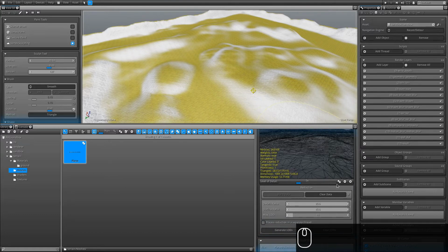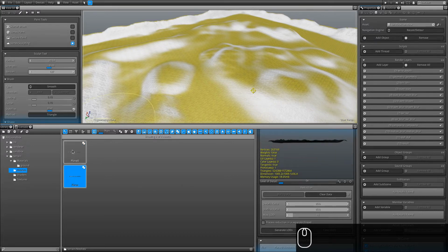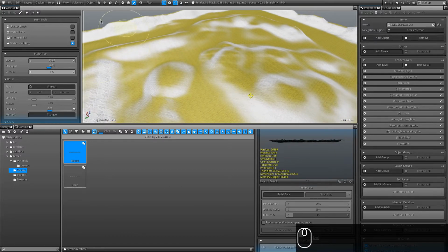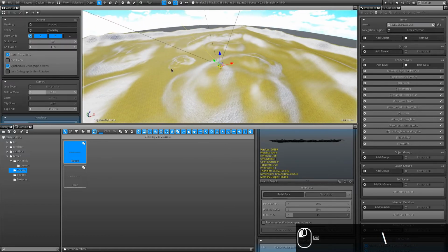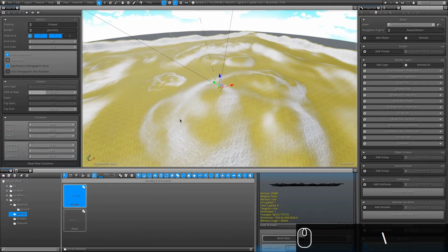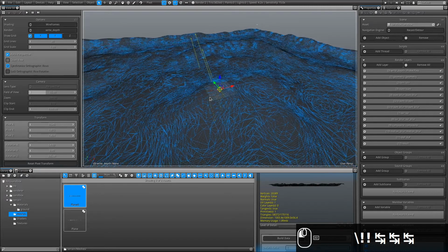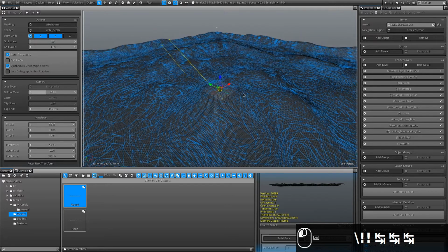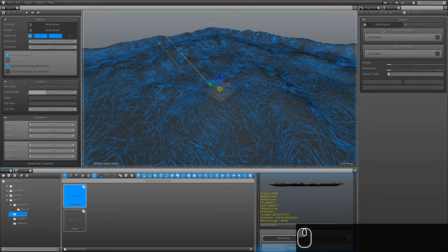And instead of applying it, what I'm going to do is generate a new mesh out of this that is going to be available here. And if I go back to my main mode and restore back here, I am now going to go on my right depth render layer, which is my first render layer, and simply drag and drop my new geometry here. If I enter wireframe, I can see my geometry here. And I'm actually not really interested in rendering this geometry. All I'm interested in is generating a static mesh out of this that will be used for collision.